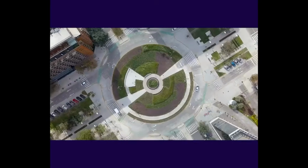Is it two CPUs? Is there anything else? So strangely enough, there's really no fault tolerance in the AGC. They just counted on it being reliable enough for the mission. On the Saturn booster, the LVDC computer had three copies of everything, and two out of three would win. So that had reliability built in. But the AGC, if something went wrong, they would probably have to come home. But fortunately, it worked fine for all the missions.